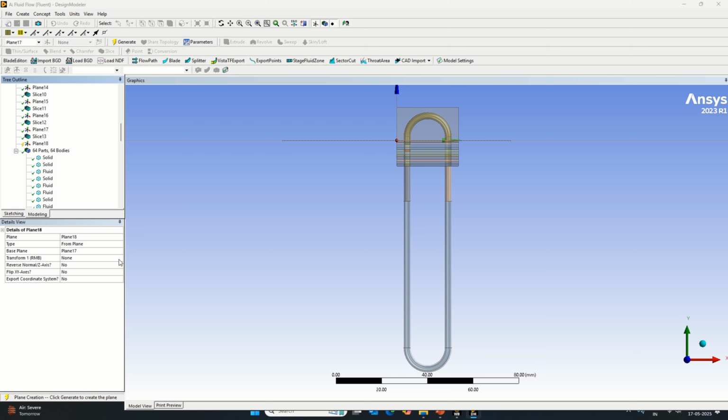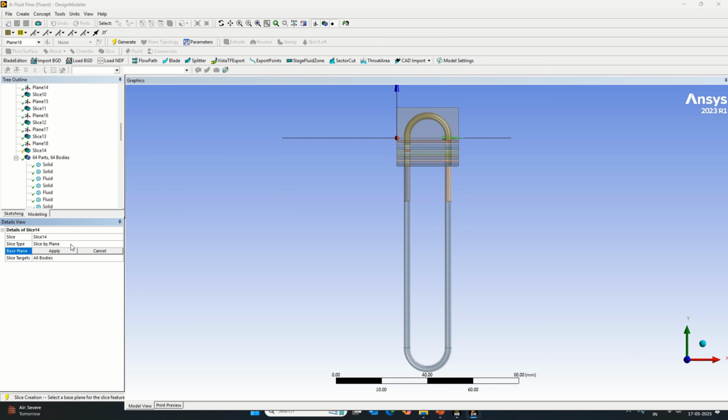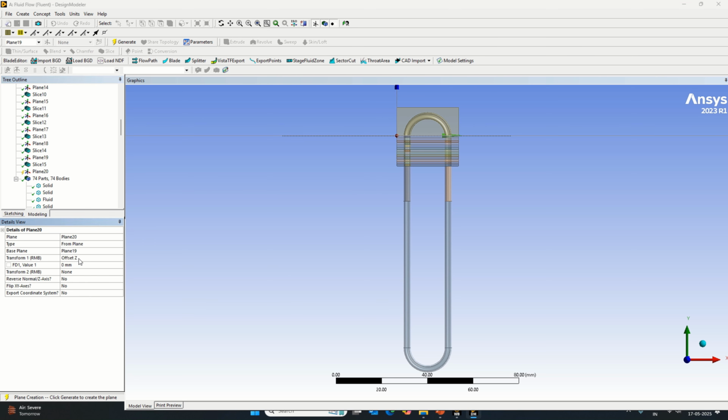So not necessary, I have provided thickness that is equal to 1 mm. You may have your own different value. Just make it slice and make it generate here. So just one more time, here offset z 1 mm, make it generate, and then you have to do the slice operation. Till the time we reach the other end, we'll do the same task of doing the slice.